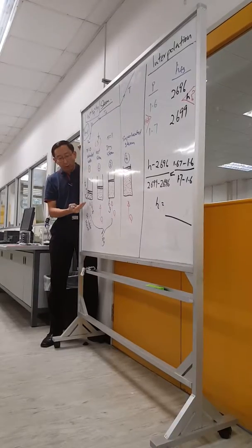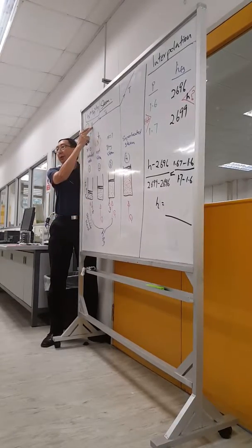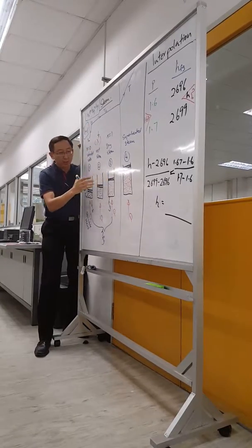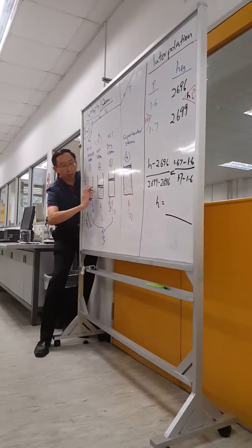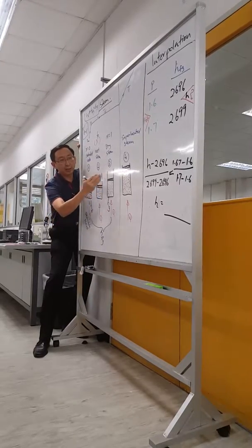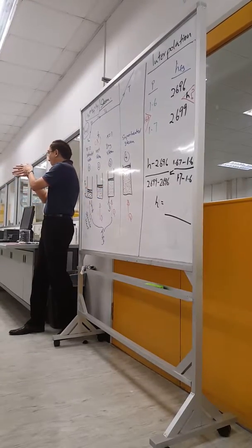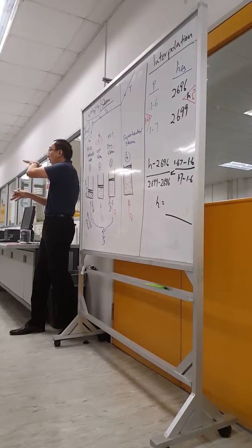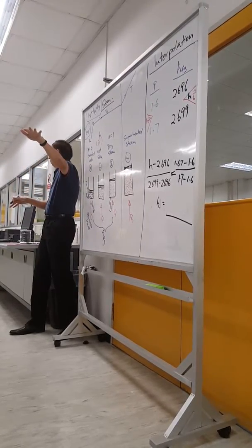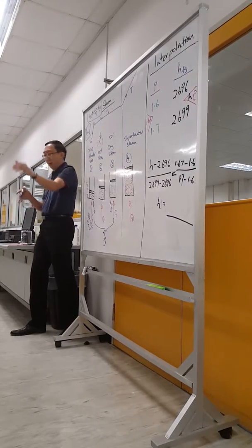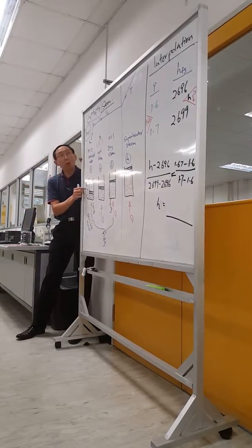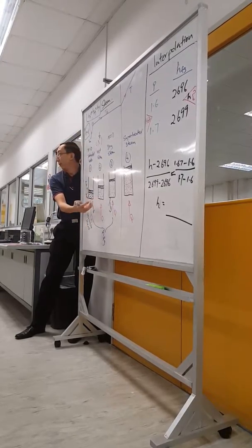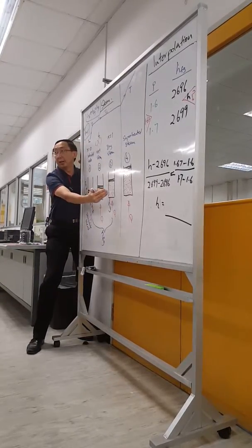Stage 1, from room temperature to saturation temperature. This is boiling temperature. Stage 2 onwards, when they change from liquid to wet steam to dry steam, during this phase change from water to wet steam to dry steam, temperature remains the same. From water to wet to dry? Yes, here to boiling. Then from boiling onwards, I must add on heat, right, to change it from this to this.